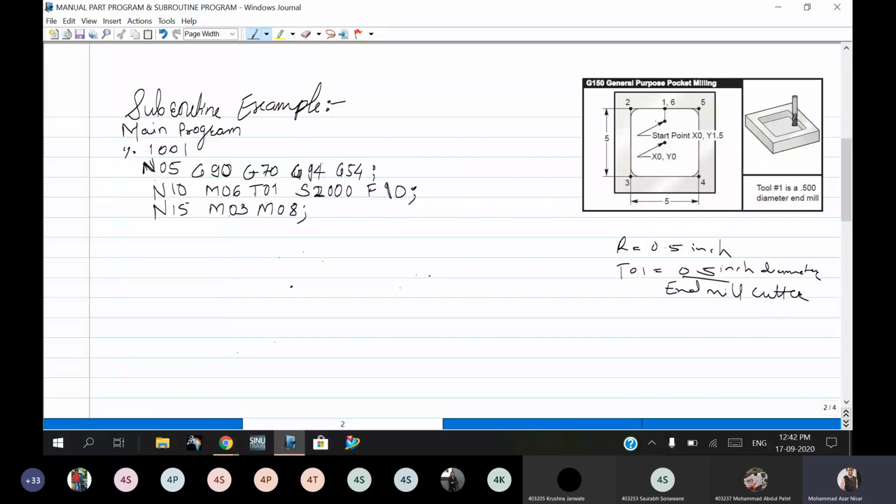Next, you have to give the cutter height compensation. For the height compensation, you have to use the code in positive or negative. Suppose they have specifically told you the height of the cutter used for the previous workpiece zero, and it is smaller in size, then you have to use positive. If it is larger in size or length, then you have to use negative, and write the value of that. So how to write it?